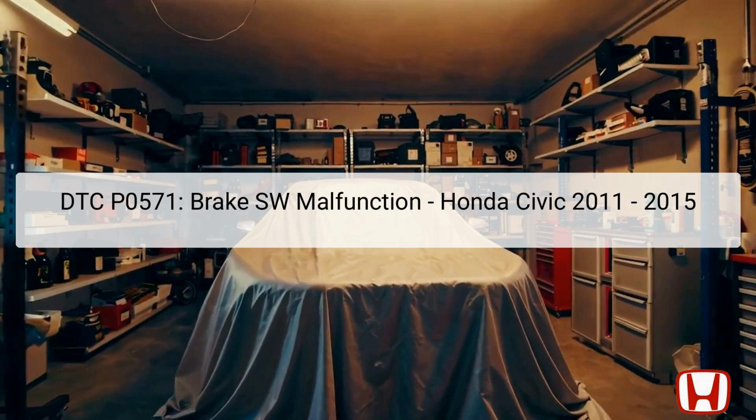When the brake pedal is pressed, the switch should activate the brake lights and inform the engine control unit (ECU) of the action. A malfunction in this switch can lead to improper vehicle behavior, affecting safety and drivability. Symptoms might include brake lights that stay on or do not illuminate when the pedal is pressed. Thus, the implications of this code are significant, not just for functionality, but also for the safety of the driver and others on the road.